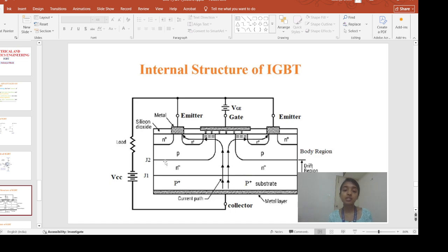Due to this reverse bias, no current can flow from emitter to collector, and no current can flow through the device. Whenever there is a reverse bias, that is an open circuit, so the supply cannot reach there. Your circuit is completely disconnected from the rest of your circuitry, so you may get only a little amount of minority carrier current.